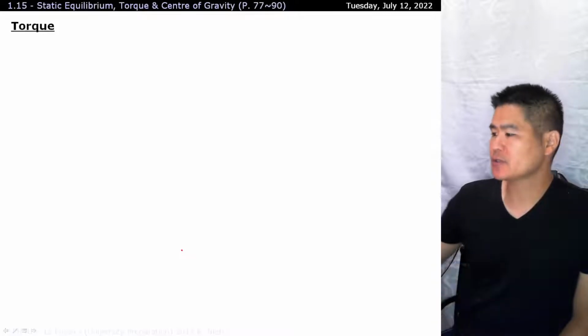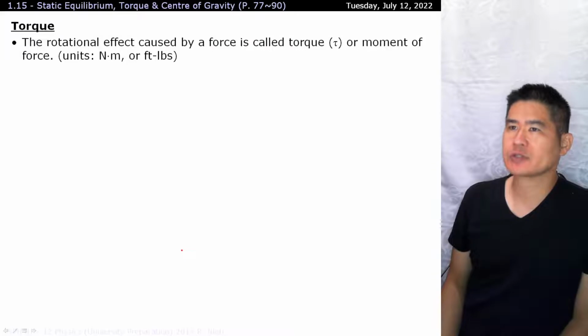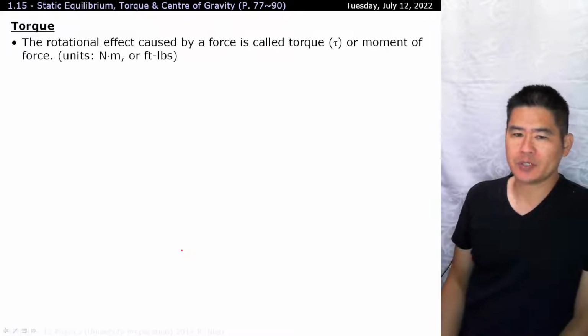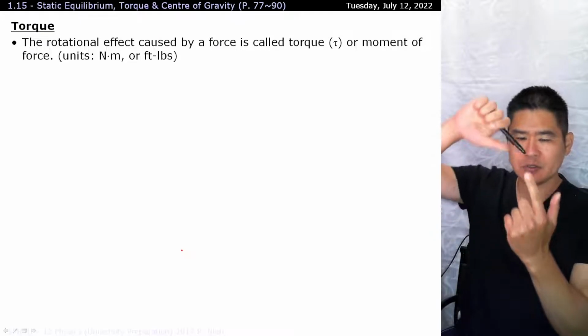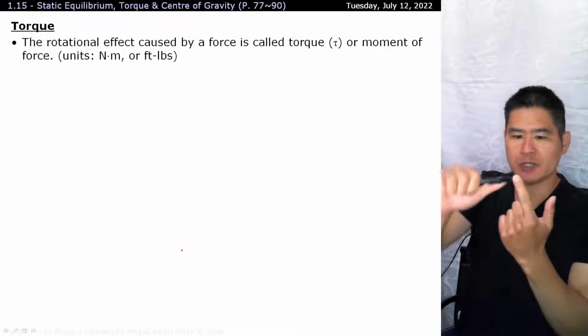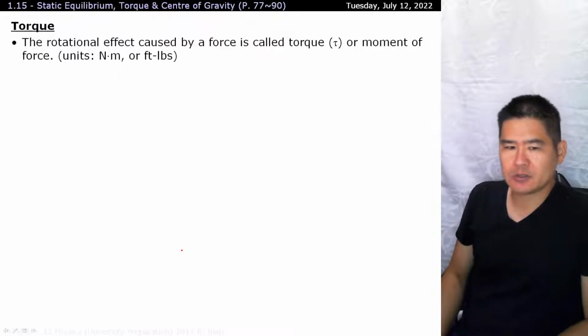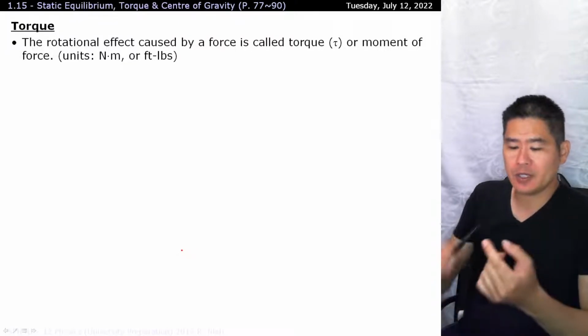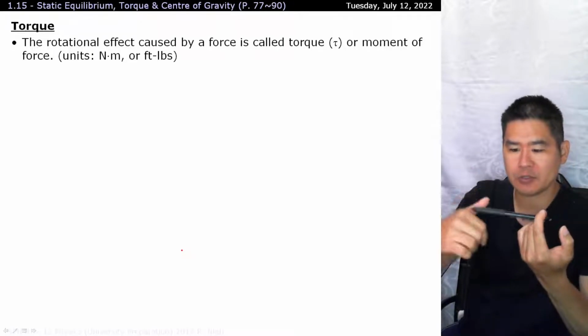Okay, so torque. What exactly is torque? That's the rotational force, all right, on a particular fulcrum. All right, so that's torque. If I'm trying to use a wrench here and I'm using the wrench to, I don't know, tighten my finger for whatever crazy reason. Okay, and the torque formula is fairly straightforward. It is the force applied at the edge multiplied by the length of the arm used towards cranking.